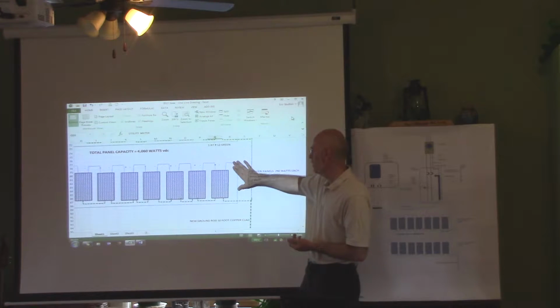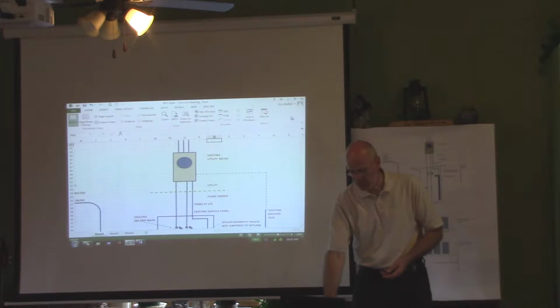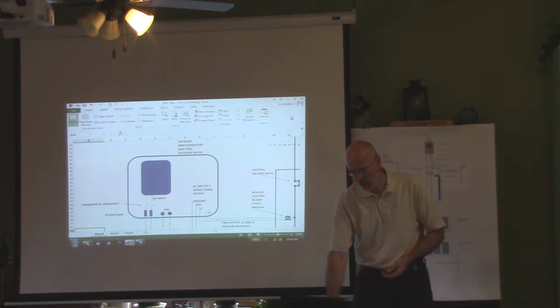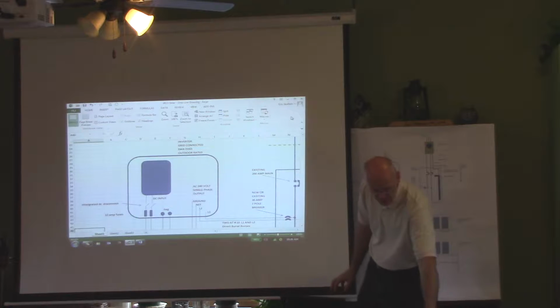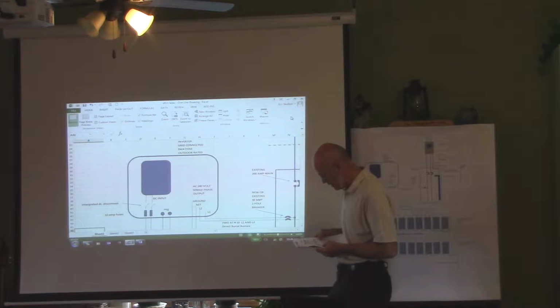So the wire's got to be happy, the solar panel's got to be happy, and then we really have to make sure the inverter's happy. The way we make the inverter happy is we stay within the specifications of the equipment. The equipment says we can give it 230 to 500 volts, but then it also says, if we go a little further down, I'm looking for DC amps. I didn't look this up ahead of time, but it should be in here. Current DC.